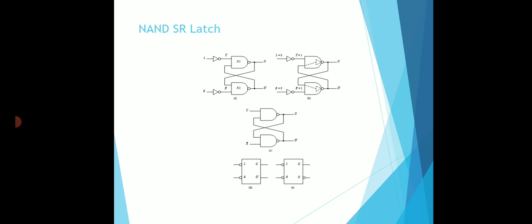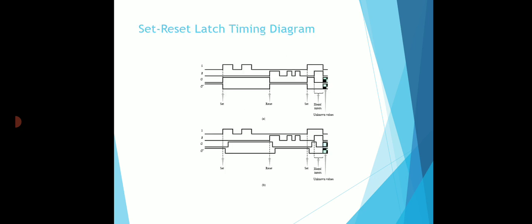The operation of this SR latch can be modified by providing an additional control input. That is, the state of the latch can be changed here. While seeing the timing diagram, this control signal will be an enable signal, separate from the other two inputs. When an indeterminate condition occurs, meaning when all the three inputs are equal, this condition makes it too difficult to manage both things.